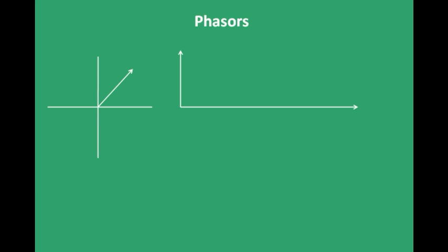Now, why do we need these phasors? Because till now we have dealt with those situations where voltage and current were in phase. I mean, they were reaching their respective maximum values and minimum values at the same time. But when you have an inductor or capacitor in your circuit, then they'll have some phase difference, or they'll not reach their respective maximum values at the same time. And in those cases, phasors are very handy to analyze the situation. I'll tell you how to read them.